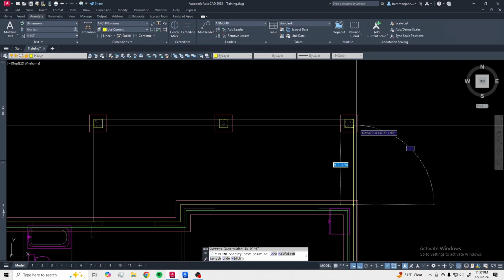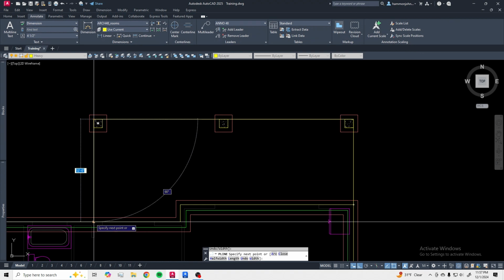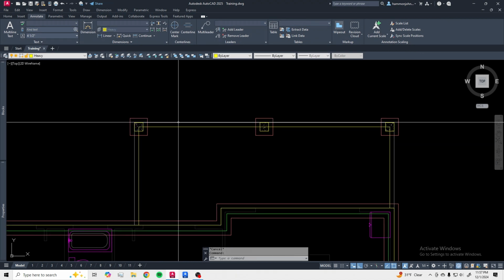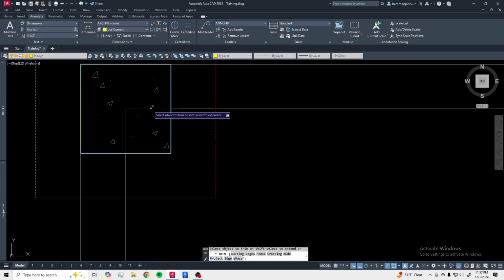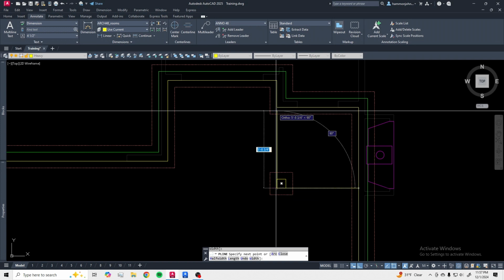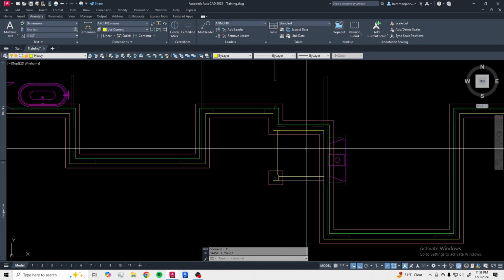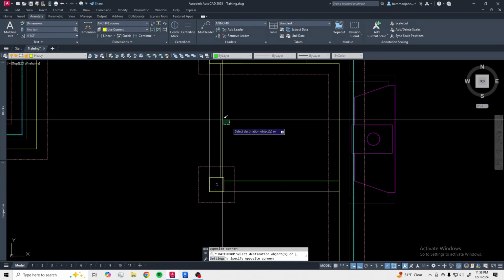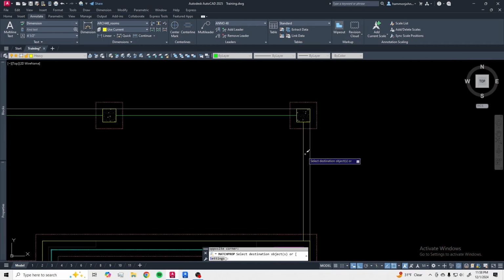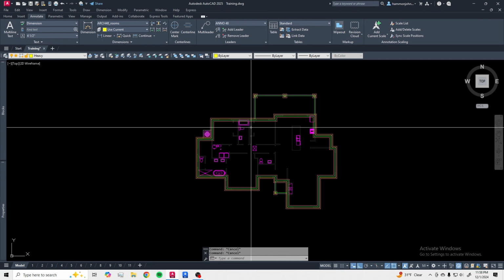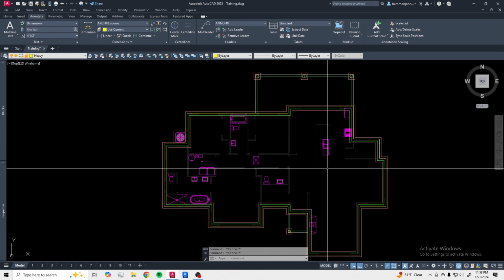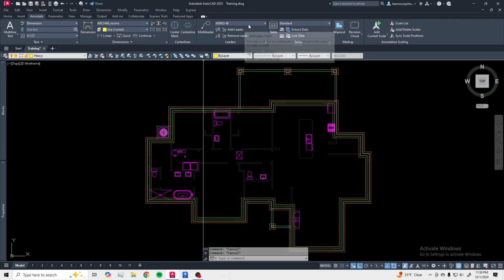We also want to go in and represent a 6-inch turn down on these concrete pads on the exterior. Then we can trim that out on each post. Similarly, we are going to go through and put each of these on the above below. All right, from here, all we need to go do is annotate our foundation plan.